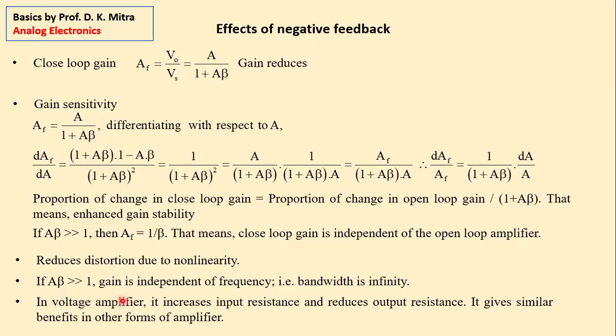Amplifier. Now, I discussed earlier the voltage amplifier, where input is voltage and output is also a voltage. Your voltage amplifier design should be such that input impedance is high and output impedance is low.